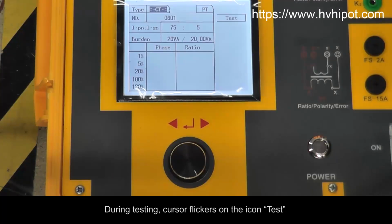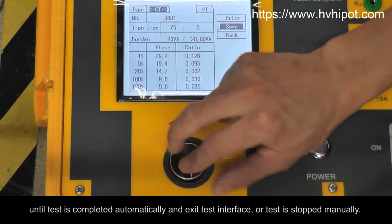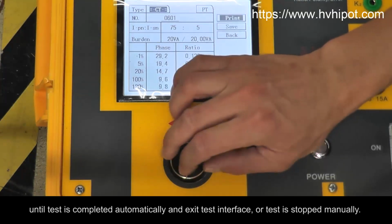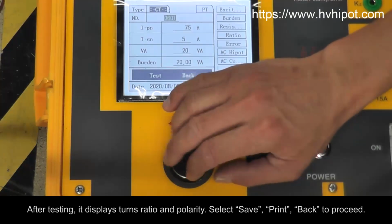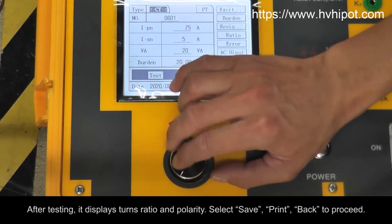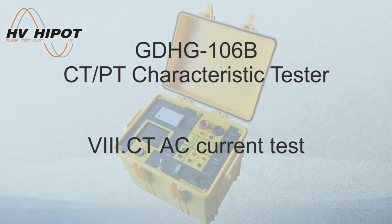During testing, cursor flickers on the icon Test until test is completed automatically and exit test interface, or test is stopped manually. After testing, it displays turns ratio and polarity. Select Save Print, back to proceed. Terminals in the same color are in-phase terminals when P1 of tester is connected to P1 of CT, S1 of tester to S1 of CT. Subtractive polarity is displayed.